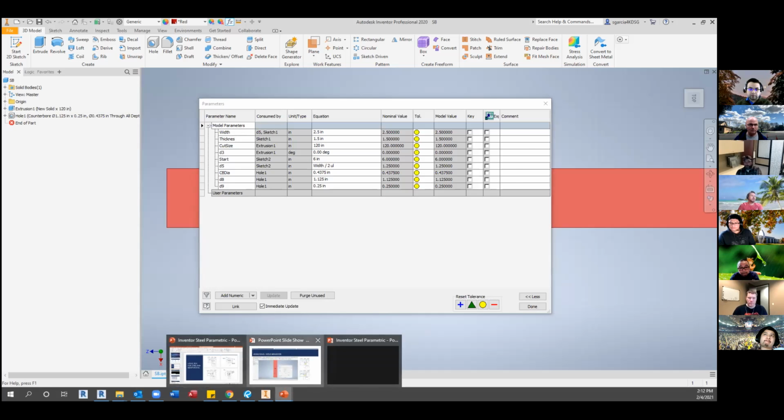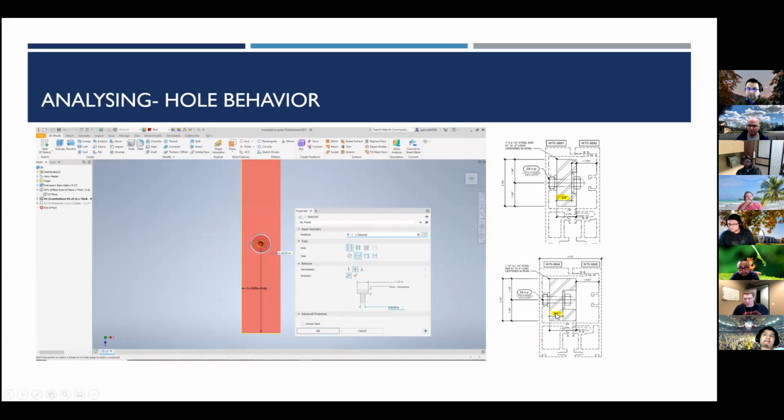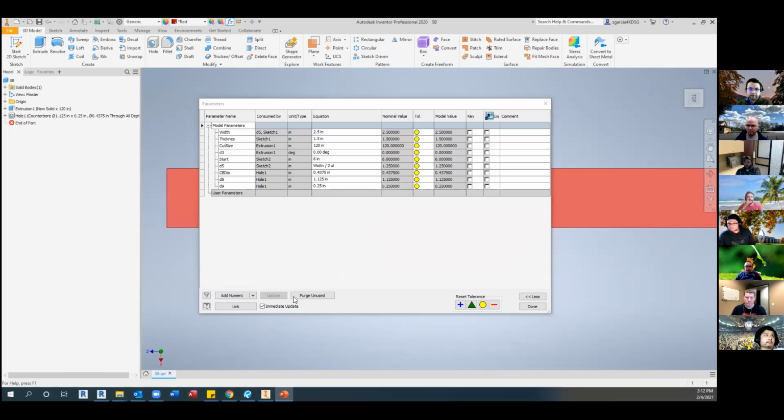Every time, this is the remaining here, 3 1/4. That's a constant every time. So if I have a 3/4 steel bar, I'm gonna keep the same consistency between all my parts. So I need to create these parameters on Inventor, and that's gonna be called a user parameter. The only thing I need to do is go to add, I'm sorry, numeric. So let's call it seed, and you can call it whatever you want. Seed is gonna be 3/4 of an inch every time.